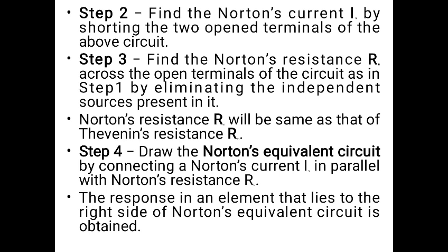Step 4. Draw the Norton's equivalent circuit by connecting Norton's current I in parallel with Norton's resistor. Step 5. The response in an element that lies to the right side of the Norton's equivalent circuit is obtained.